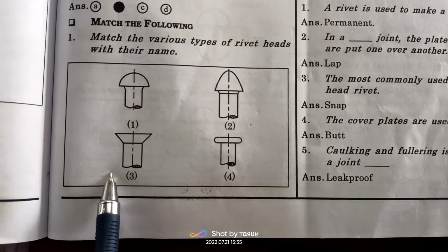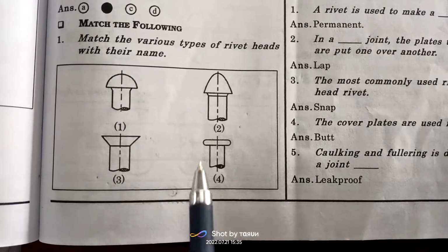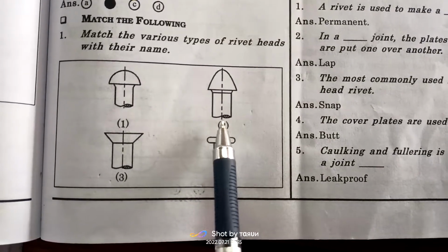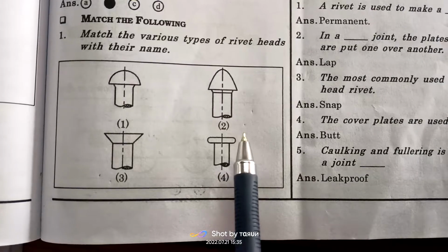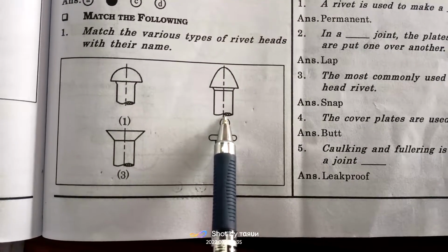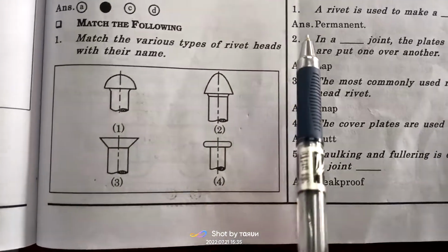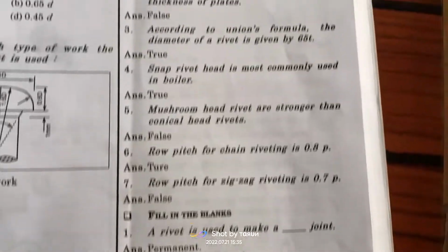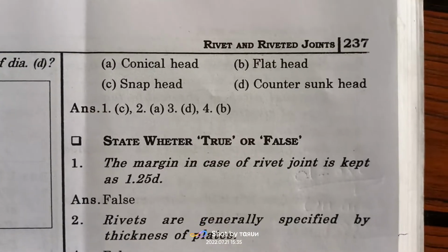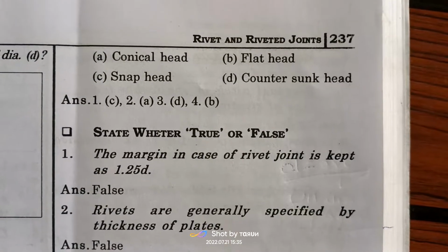And fourth one is flat head rivet. This is the cut section, the section line drawn at 45 degree with 1 to 2 mm gap to show the cut section of any machine part which is cut. So you can see the options: first is conical head, flat head, snap head or countersunk. These four are the options.